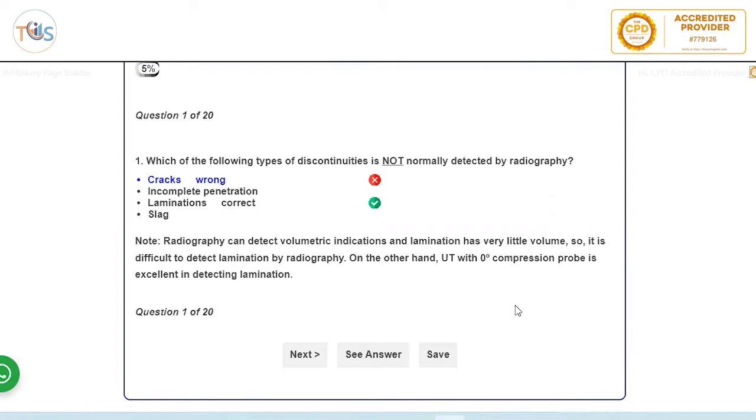As a result, you see a lighter version of that brightness on the radiographs. The only exception would be gas tungsten arc welding, where you have tungsten inclusion from the electrode tip, and tungsten is a very dense material, denser than practically any other base metal, and hence you see it as darker. So normally, anything brighter than the surrounding area is a defect or an indication you can see.